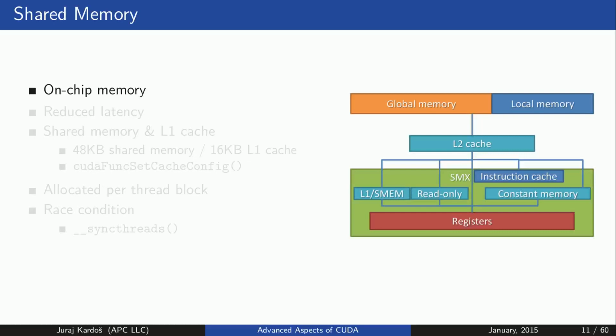We have seen that memory transfer between host and device is done at 8 or 16 GB per second in the best case. We will see that PCI Express can be shared among multiple users or peripheral devices, therefore the bandwidth can be even more reduced. Memory access to global memory has bandwidth reaching 200 GB per second, while on-chip shared memory has bandwidth of 1600 GB per second and much lower latency.